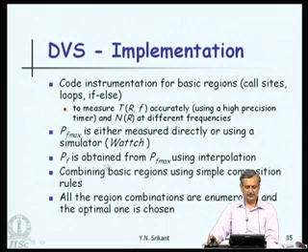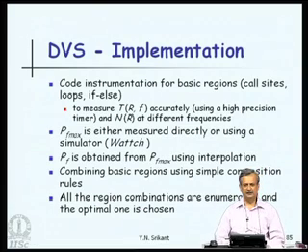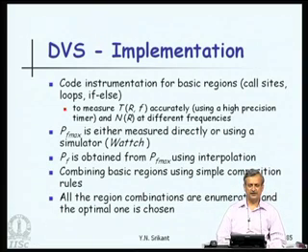If this is not going to be linear, then it is possible to change the frequency, run the program at that particular frequency and measure the power. So, we could do this for a couple of frequencies and then fit a curve and calculate the power consumption at other frequencies using this fitted curve.